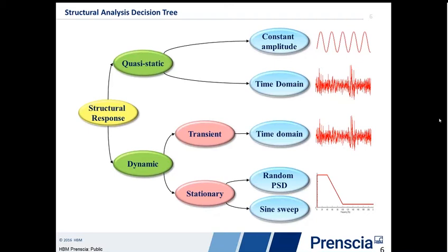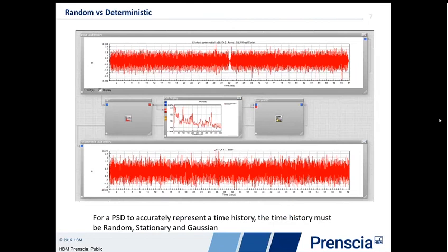If we have loads where we can physically predict when things are going to happen, for example, I know on this particular road surface I have a series of potholes I hit every time, then we really want to go to the time domain. When we have loads that are basically random in nature, steady state dynamic, it makes sense to work in the frequency domain. Just trying to characterize that.